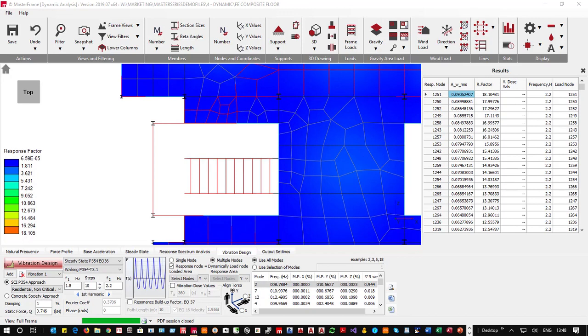So it's all at serviceability limit state. You would have previously done a full design, not as an FE slab, but as a simple composite frame to design your beams and your columns and things like that in the structure. And of course those will be ultimate limit state, but not the vibration analysis, the dynamic analysis.